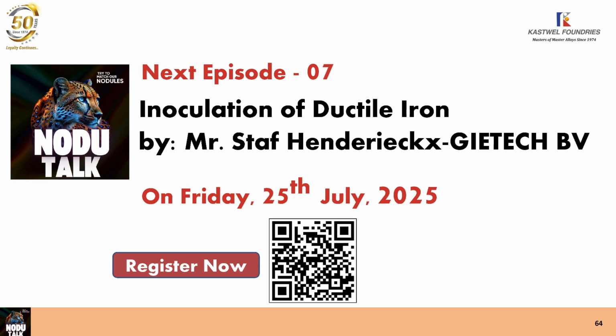If the temperature is too low, the dross will stay all over your casting because it cannot float up. When the temperature at the end of the pouring is still liquidus temperature plus 30 to 50 degrees C, the dross will float up and you will find it at the top of your castings, where with some extra machining stock you can remove it.